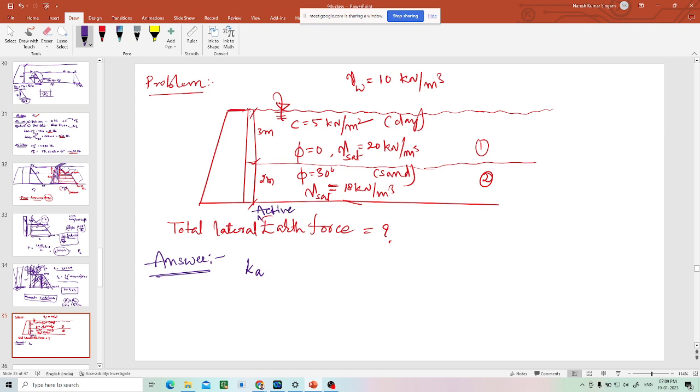See, for passive and at-rest earth pressures, you go through any material. I am just solving lateral active earth forces in this class. Now the concept is the same. Wherever minus is there, you just have to put plus for the passive. That's the only difference.